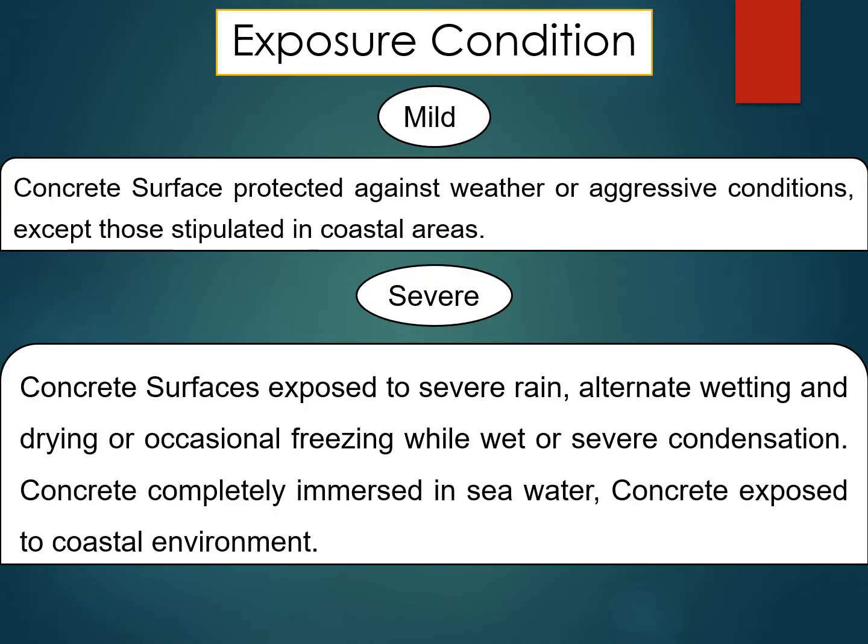Exposure conditions are defined as mild, moderate, severe, very severe, and extreme. Mild exposure condition is the one where concrete surfaces are protected against weather or aggressive conditions, except those stipulated in coastal areas. Severe conditions are defined as concrete surface exposed to severe rain, alternate wetting and drying, or occasional